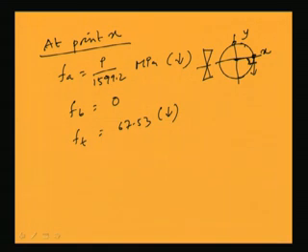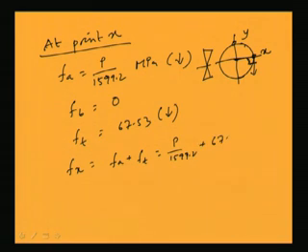So, I can find out the resultant stress at x, say Fx will be Fa plus Ft finally. So, P by 1599.2 plus 67.53, and this has to be less than the allowable stress.